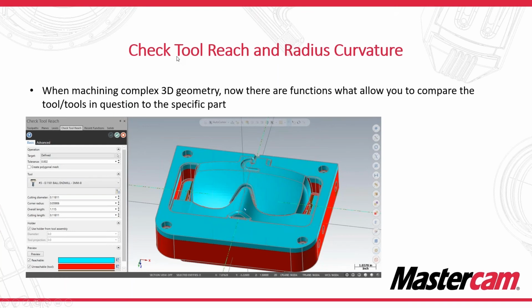All right, now we're going to get into the 3D machining. One of the new features that I personally really like when it comes to 3D machining is the ability to check our tools and what we can reach and what we can cut. So that's what this new check tool reach function will do. I'm also going to go over radius curvature because it's an older part of Mastercam, but I feel like a lot of people don't use it or don't know about it. So I'm going to show you guys what that is too.